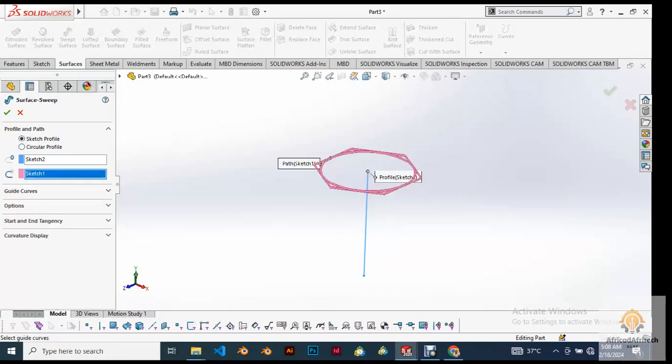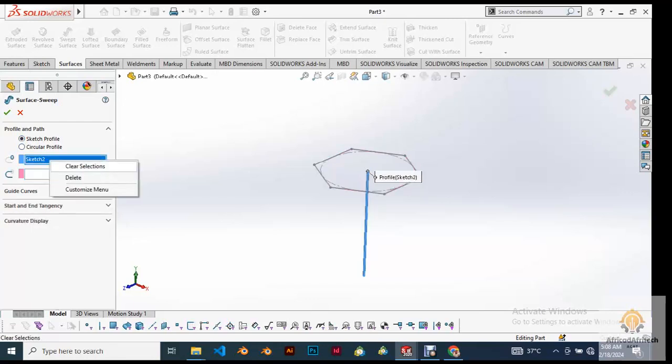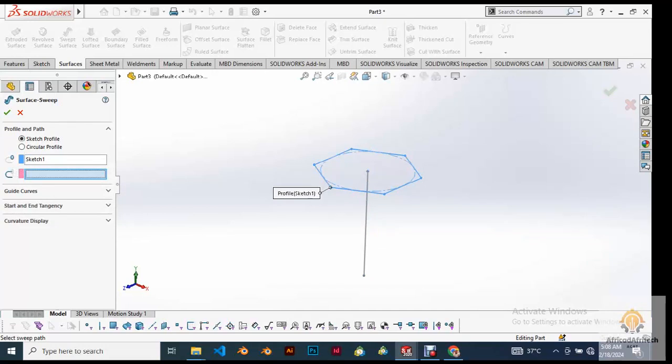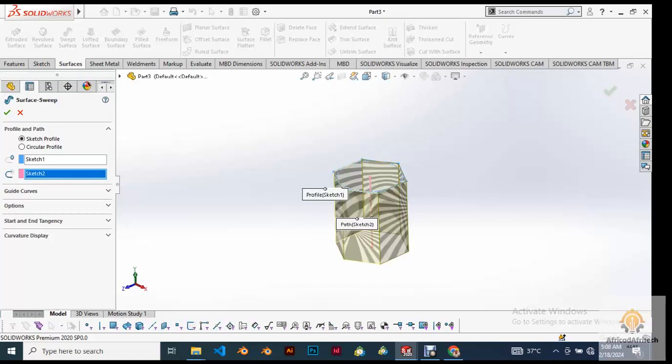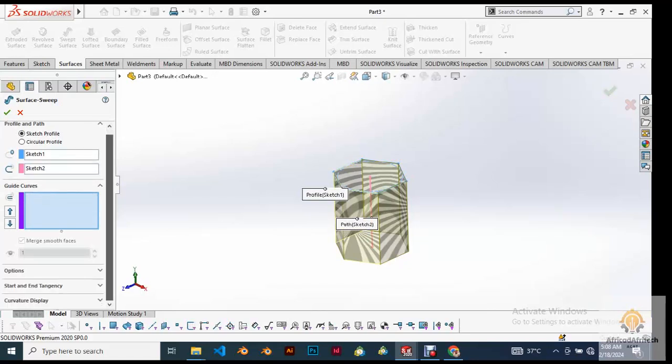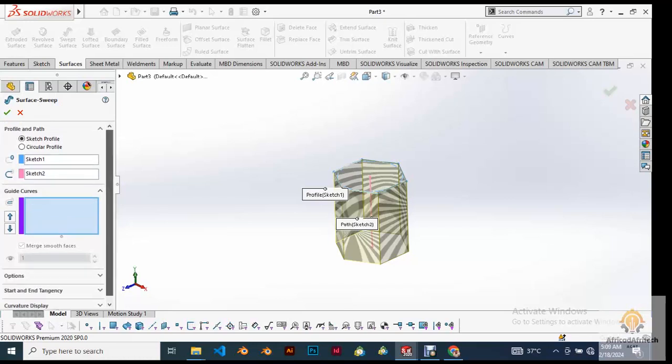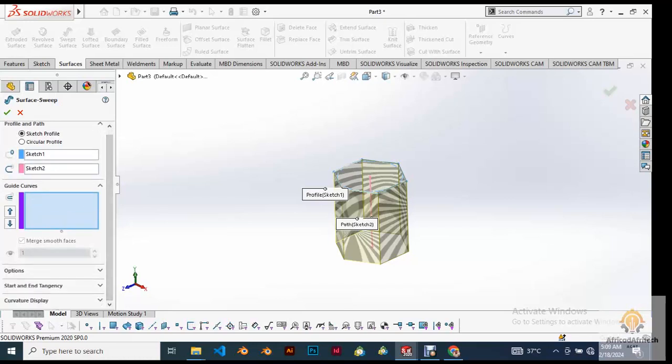You can see your sketch profile. So your sketch profile, I've already defined what the sketch profile is, so I will not be going back. So this is now your sketch. You click on your sketch. So now this is asking for a profile. So you click this is your profile, and this is asking for your path. So you click this. So did you see that it extruded this profile along this path? So that's what sketch profile is all about.